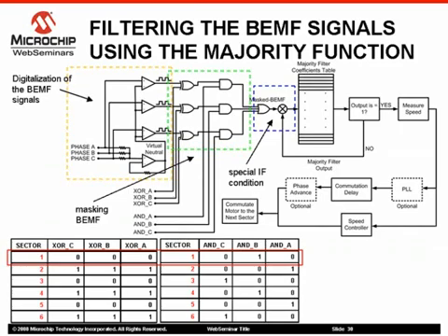The 64 values represent the 2^6 possible combinations that the 6-sample window could have for the active masked back EMF signal. Each value on the lookup table is a pointer to the next signal state over time. The filter is always looking for a true to false change at the output of the logic test condition. If this true to false condition is detected, the filter looks for 3 consecutive false states to validate that a zero crossing event occurred. A true to false condition at the output of the logic test represents a zero crossing event, and therefore a commutation on the rotor, which occurs after a delay.